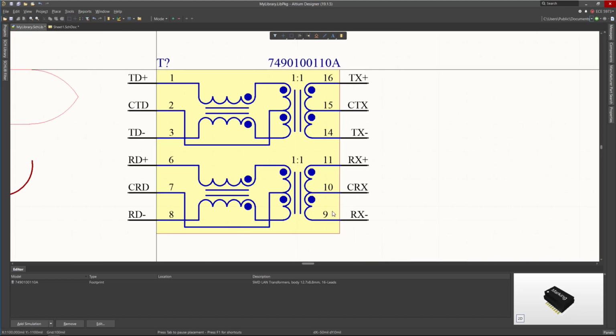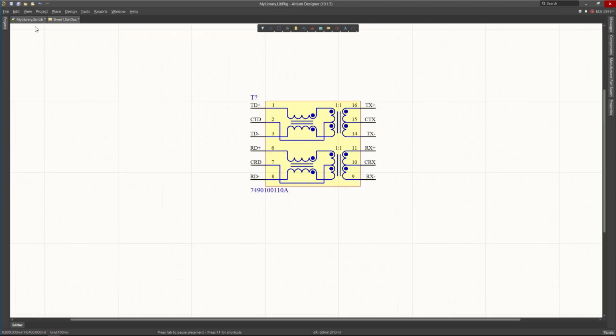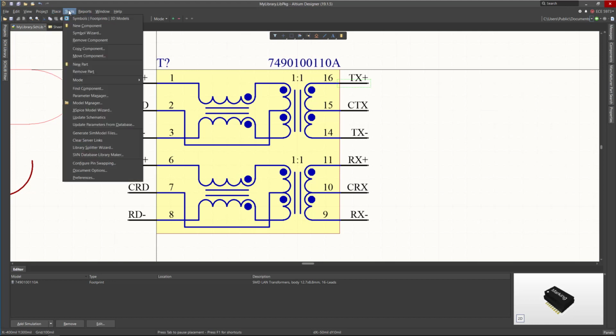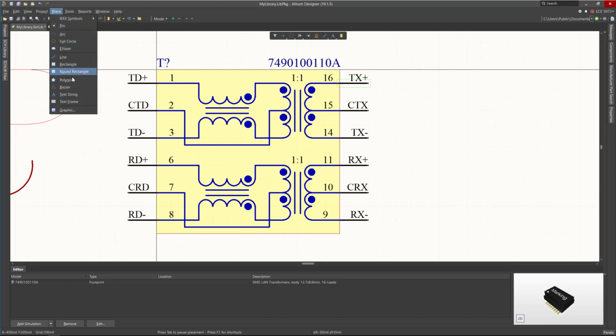And when you create these lines inside, these are not pins. When we talk about the grid, snap grid, 100 mil or 50 mil, we are talking about placing the electrical pins in here. But when you do graphical drawing like that, you can change your grid to 1 mil. That's fine, because when you go to the schematic and try to connect with the component, you are connecting with the electrical pins. You don't care about these drawings. So these pins are different from the graphical tools you have in here.